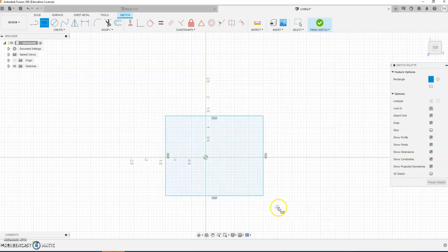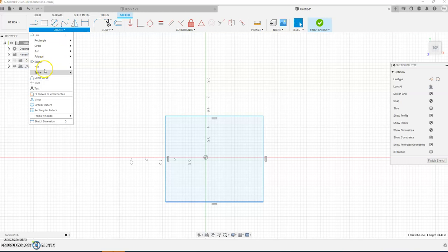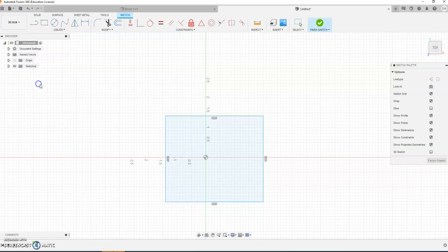Now, purposely, I made this a little bit off-centered. Just when I first did it, actually maybe not very off-centered there. So it will actually center up the way I showed you on that last drawing. Next, after we have that rectangle drawn, I hit Escape to cancel out of the command. I'm going to come up here and pick Point and draw a couple points. My point, I want it to be on the midpoint of this top line right there, and the midpoint on this line on the right there. That made 2 black dots, one on the top and one on the right. I've got my points done, so I'm going to go ahead and hit Escape.